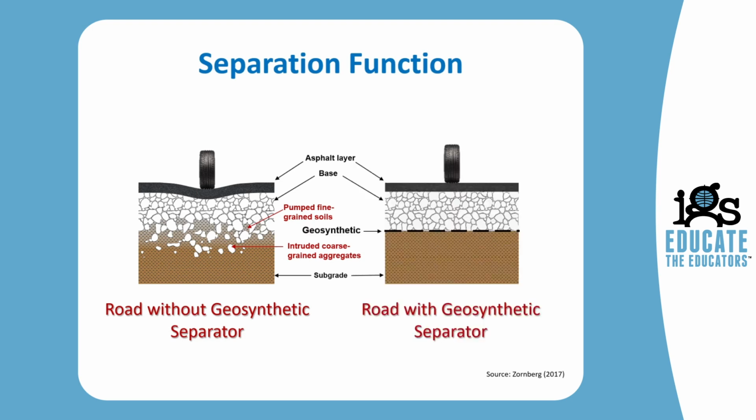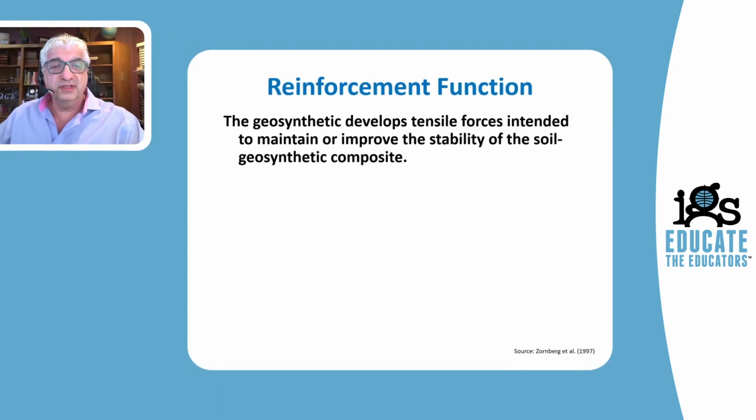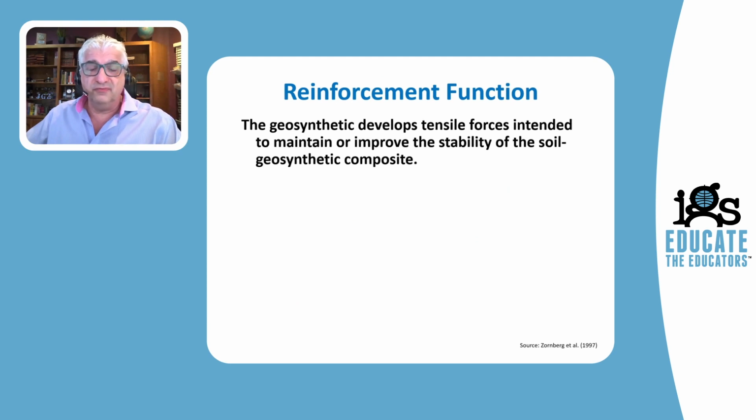The solution to this problem is comparatively simple. Let's place a geotextile separator between the two dissimilar materials to maintain their integrity over the design life of the structure.